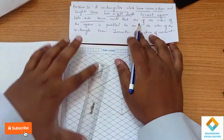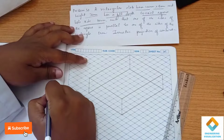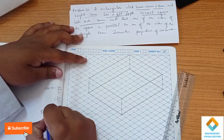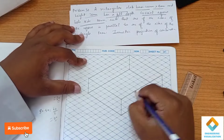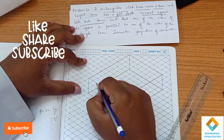Now we have to make a square hole of side 40. So we have 100 minus 40, it is 60, divided by 2 means 30. Then 80 minus 40 means it is 40, divided by 2 means 20. So on the 100 mm side we have to mark up 30. On the 80 mm side, we have to mark up 20.